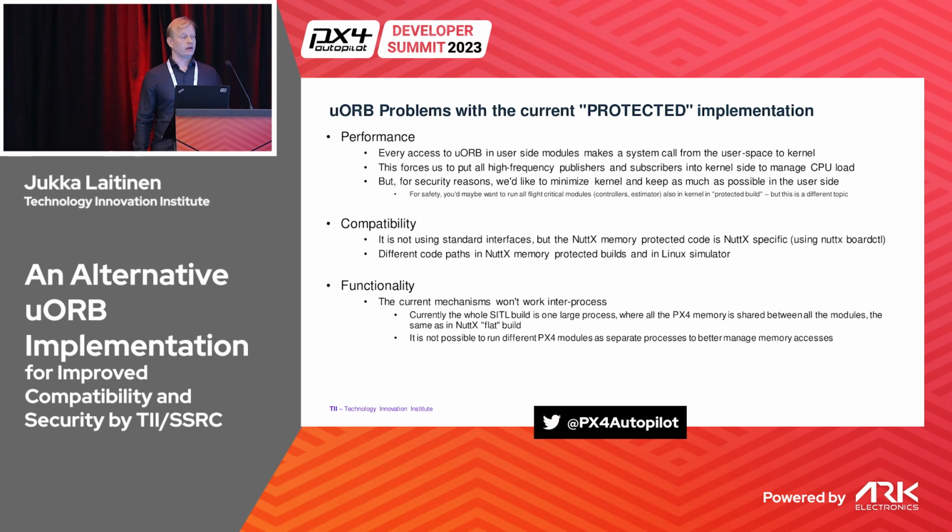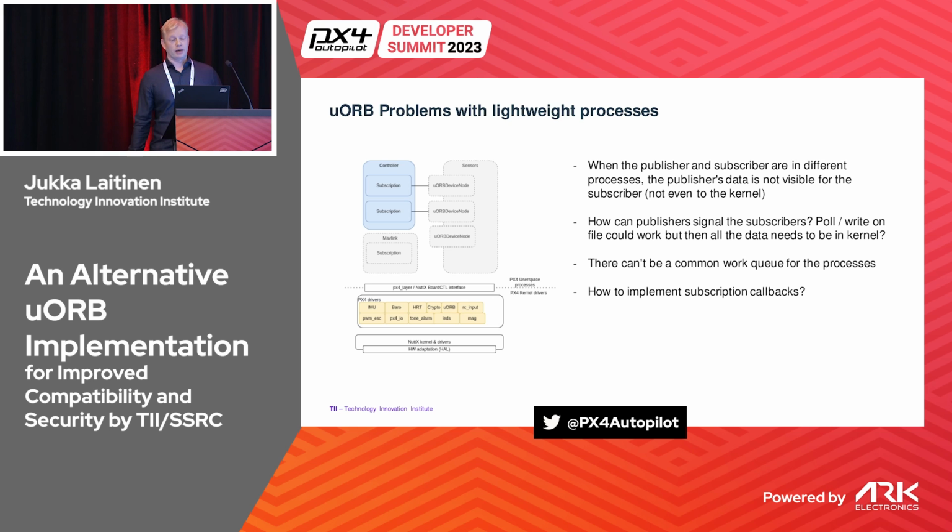And the big thing for us is that it doesn't work inter-process at all. If you launch different modules in PX4 as separate, memory-protected processes, they cannot just communicate with the current uORB. I've got a picture here that illustrates the problem.